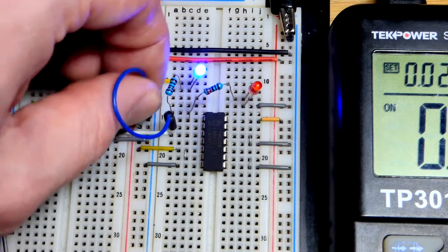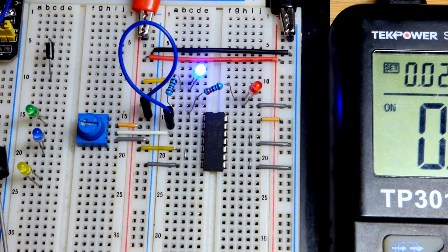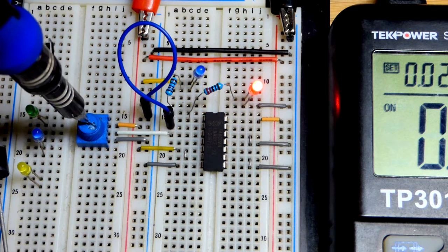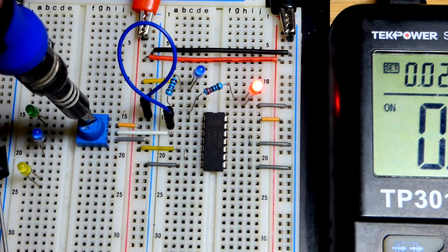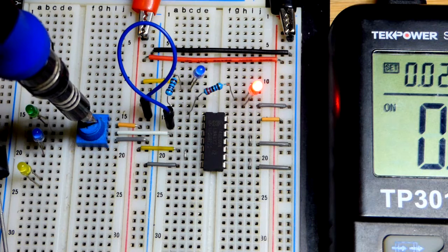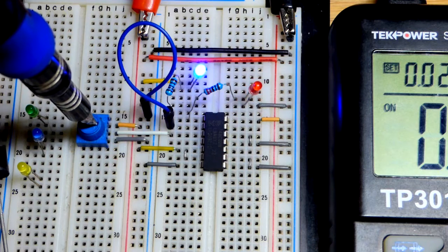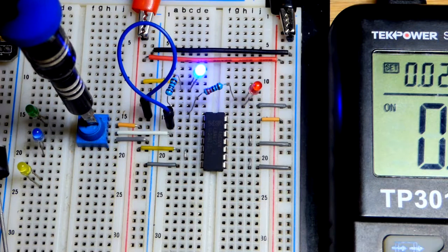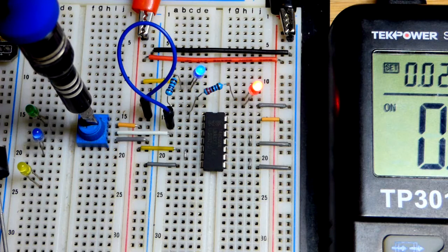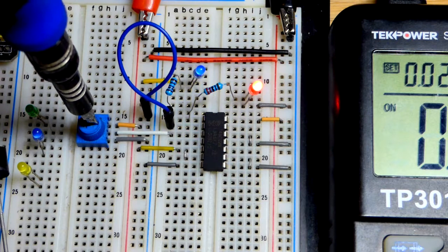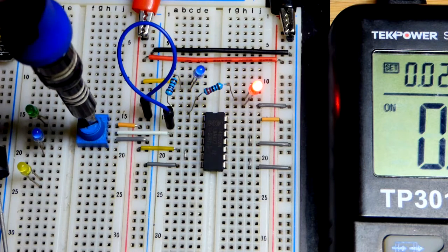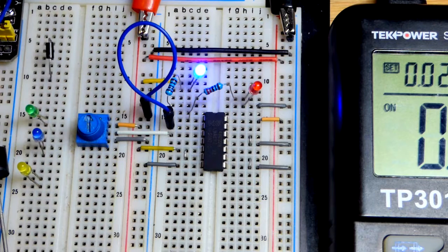Now with these integrated circuits, it's a good idea to look at how the input responds. It's really clear if it's 5 or 0 volts, and it's good to get an idea of where the middle ground is, how that's going to work. So I'm going to slowly go up, and I think we'll see the blue LED kind of turn on while the red LED is still on. There we go. Yeah. Now, working our way back down, it looks like it has more of a Schmitt trigger effect, where it kicks in right away, goes to red right there. And maybe not quite, but it looks like it goes to red easier from blue than it does to blue from red. So, in any case, that's it for this video.